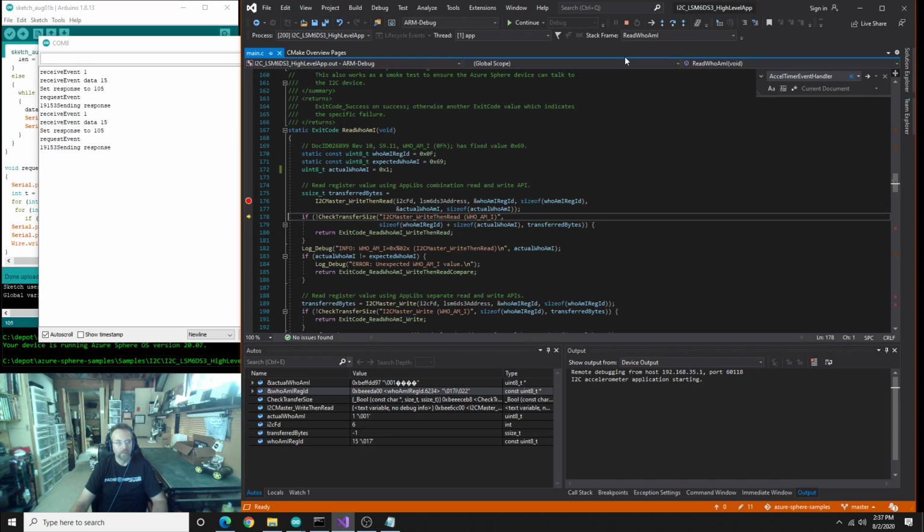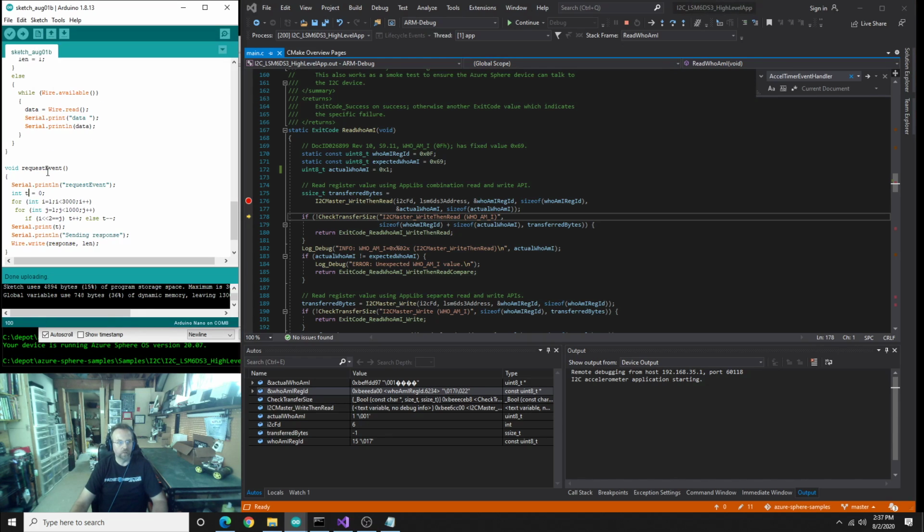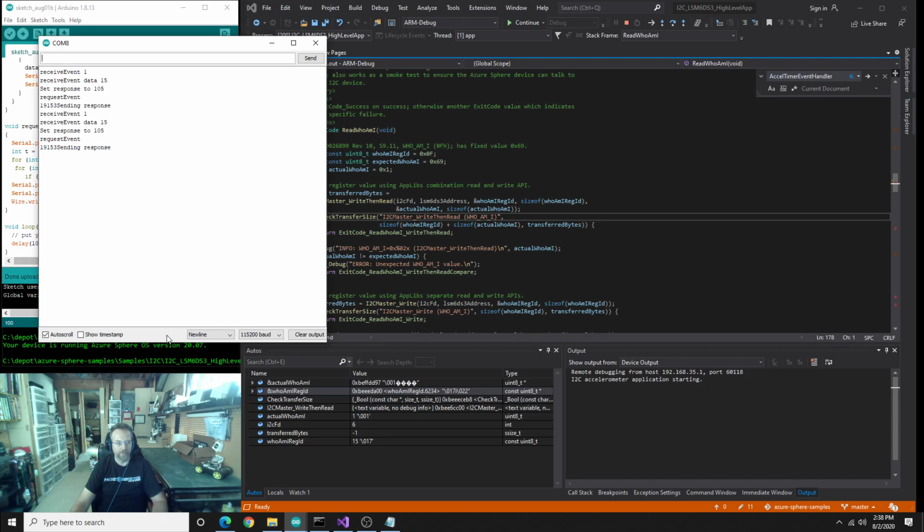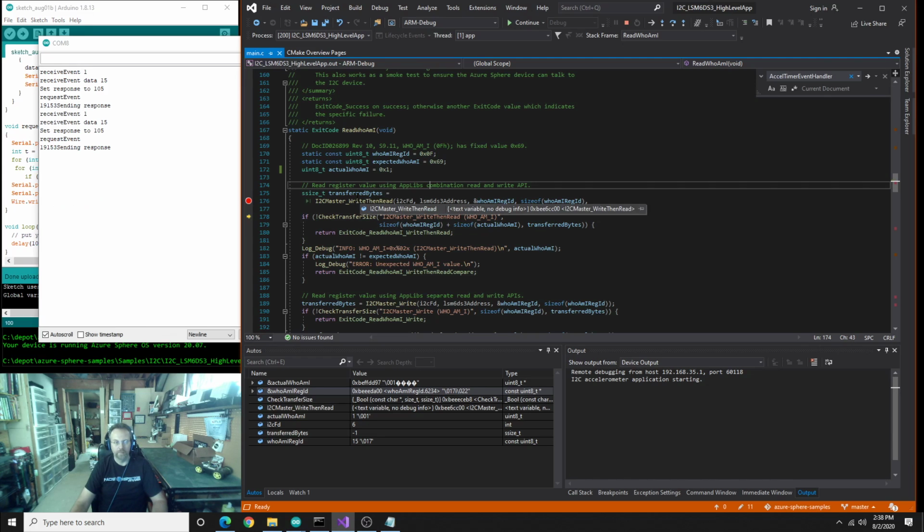Okay. Some interesting things also is while you're in requestEvent, you can't do stuff like, if you try to use a delay, the delay doesn't actually do anything. Millis, if you call it multiple times, gets the same value each time. So some of the clock stuff when you're inside of this event is disabled. But basically, we saw that it took about 3 seconds. And we saw that this failed. Okay, great.